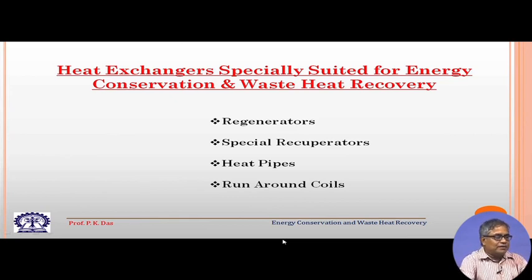Now, regenerators are of different types. Regenerator means a kind of heat exchanger in which the heat transfer is indirect, that means the two fluid streams are not mixing with each other, but they are also not exchanging heat across some sort of a solid barrier continuously. What is the working principle of a regenerator?